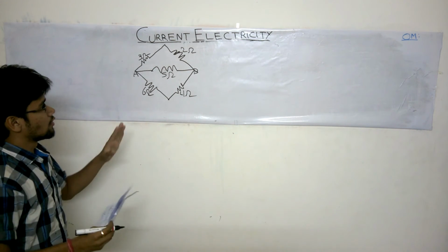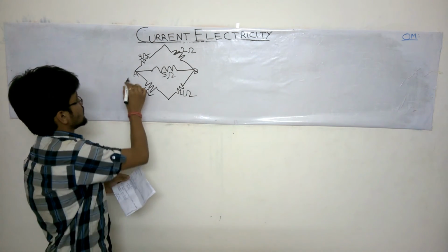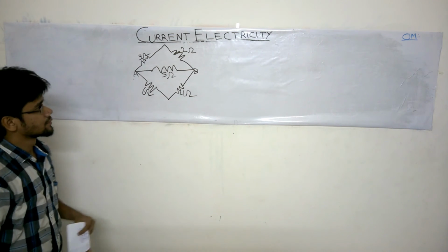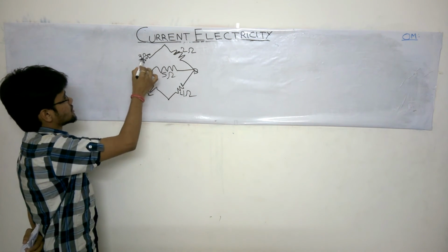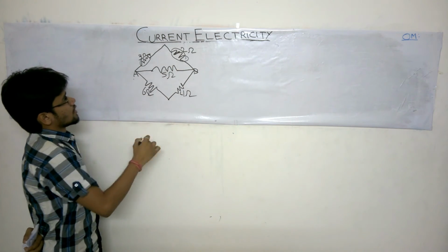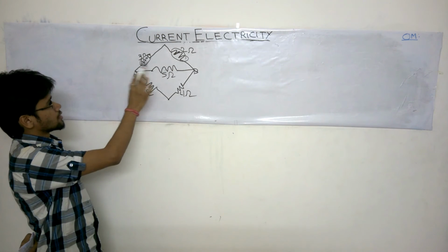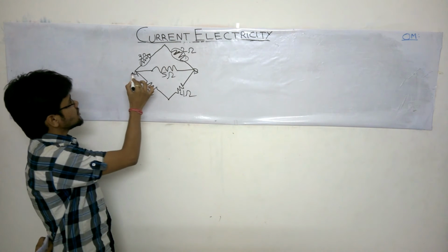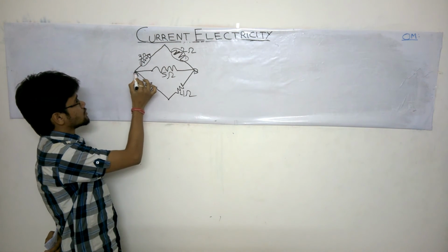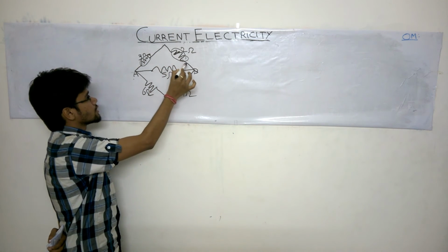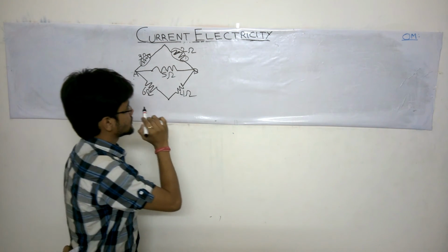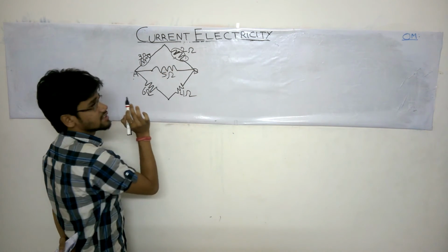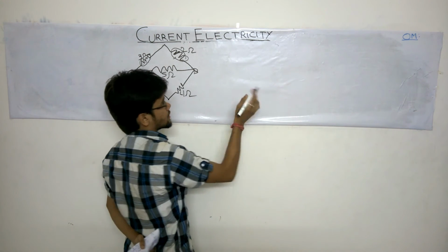Okay. Now how will we move on with this? Here we have been told to calculate the resistance between these two terminals A and B. Now what we have here, we have a resistance here, we have a resistance here. Now what can you comment on this? Whether these two resistors are in series or in parallel. Since we can see if the current starts to flow here, the same current is going in this resistor also. So what we can conclude from this is that these two resistors 3 and 2 are in series. So let us open this circuit.